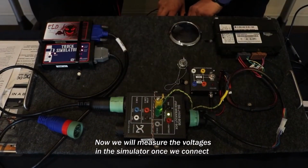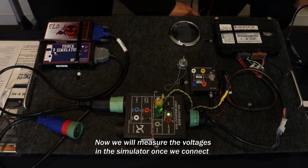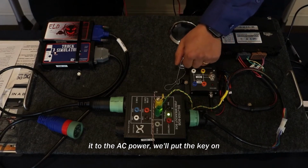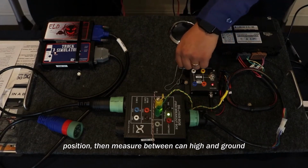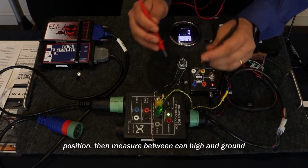Now we will measure the voltage in the simulator once we connect it to the AC power. We'll put the key on position, then measure between CAN high and the ground.